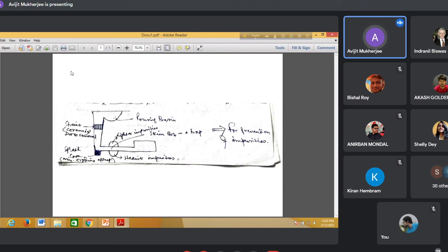So this is known as pouring basin. What is the advantage? If molten metal is dissolved with larger impurities, some foreign materials like say wooden strip, leaf, cotton, jute, all these impurities, then those will be arrested. Immediately those will be arrested.